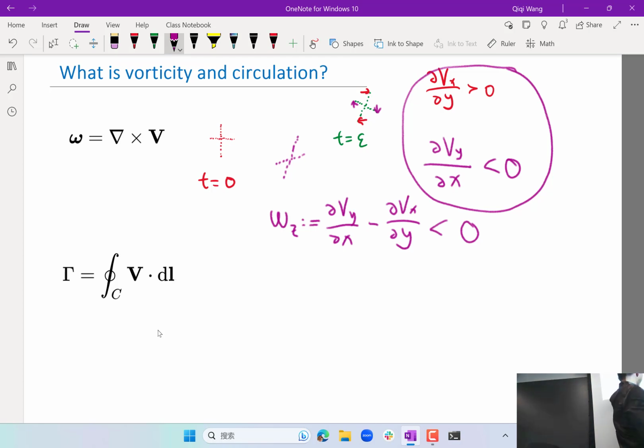Okay, so whenever you see a cross not being rotated like a solid body, but deformed as can usually be seen in a fluid, that means the vorticity can easily be 0. Similarly, another thing you can see in a fluid is that you still have an x, but the horizontal component of x has shrunk and the vertical component has lengthened. That's another type of deformation that has zero vorticity, because both of these derivatives are zero.